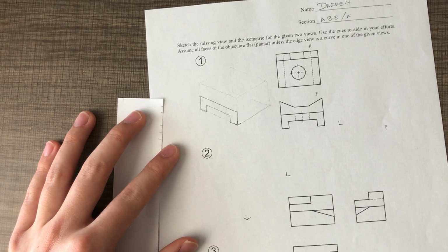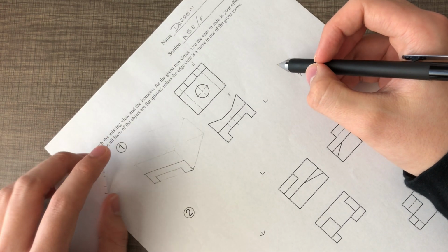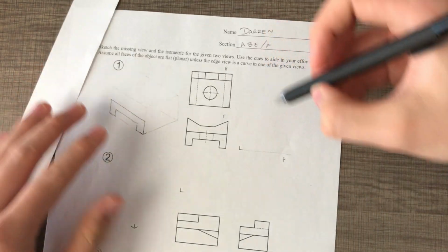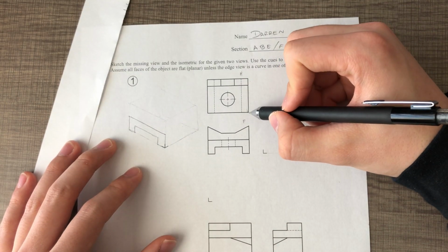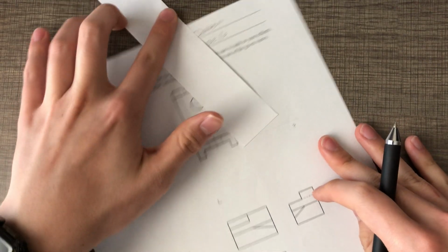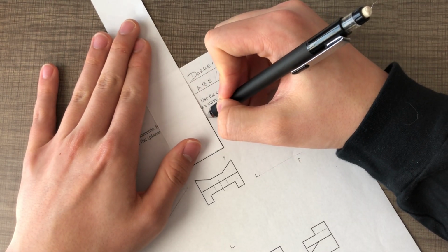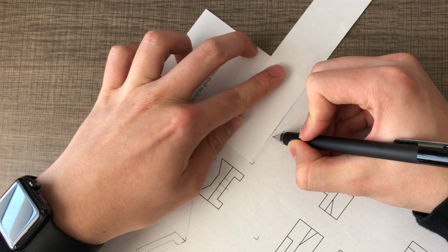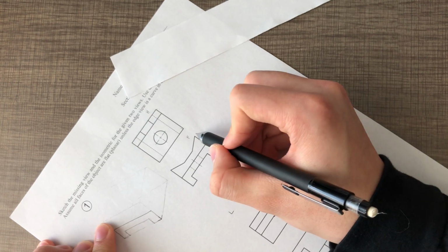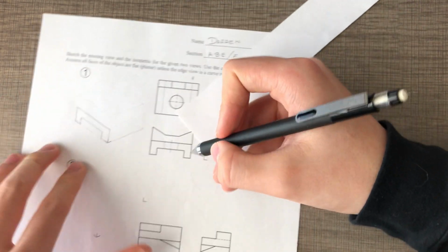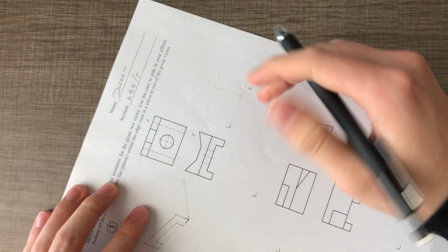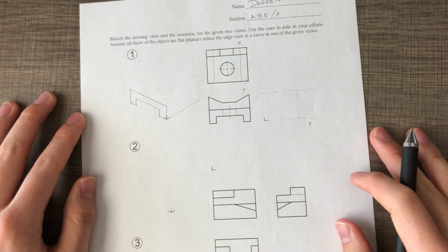Okay. What else do I need to do? Well, I don't really know what's going on the profile view yet. I can define my bounding box, of course. So the height, of course, is the same. What is the width of it? Well, the width of the profile view is going to be the same as the height of the horizontal view. So I can just use that same dimension that I got before to bring it over. So here's a bounding box for my profile view.